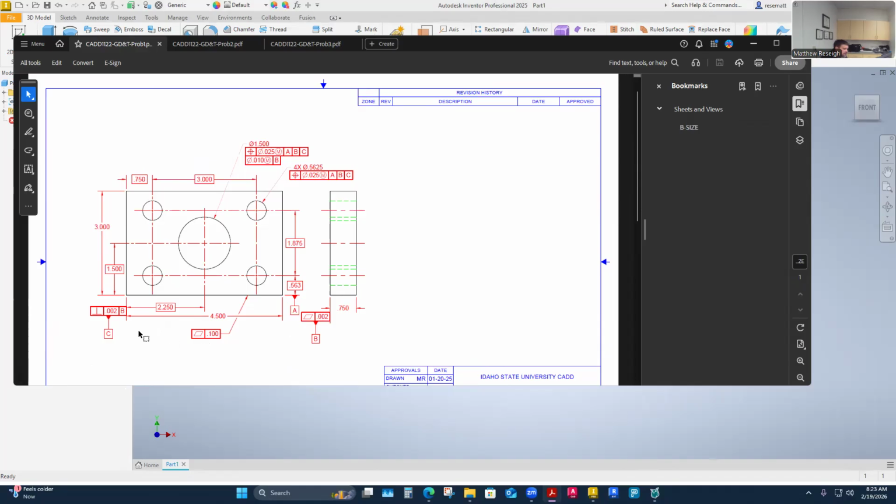So I'm not going to use these flatness and perpendicular geometric constraints. I'm just going to establish those datums. I'm really going to focus on the holes. And I'm even going to simplify the holes a little bit, and I'm not going to make this a more compound control on the center hole. I'm just going to use the position. Really, I just want to explore a position GD&T feature control frame and control.